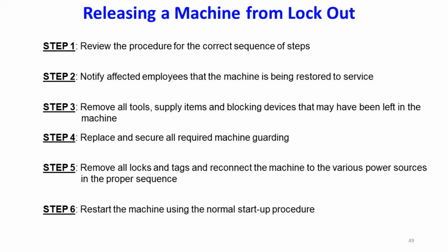Now, the most common problem with putting a machine back into service is when tools have been left inside. When the machine fires up, sometimes those tools become airborne and strike people. So always clear out the machine of tools and replace the guards before energizing the machine.